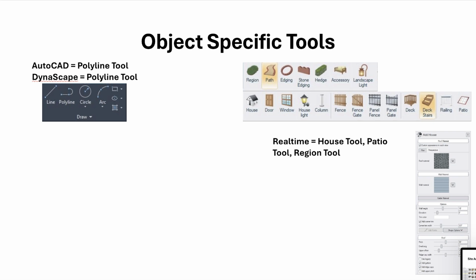Another tool is the Patio tool, which allows us to make our fire pit area as well as our flagstone patio where the table and chairs are. The differences between the two tools is the Patio tool is not conformed to the terrain of the area, and it has a preset height when input into the drawing of 2 inches, as well as a border that is able to be turned on and off.